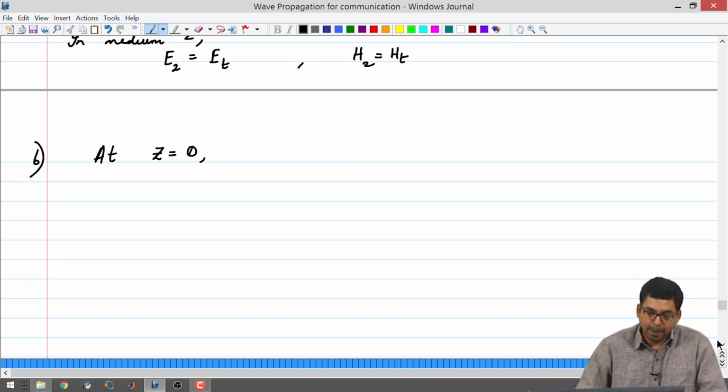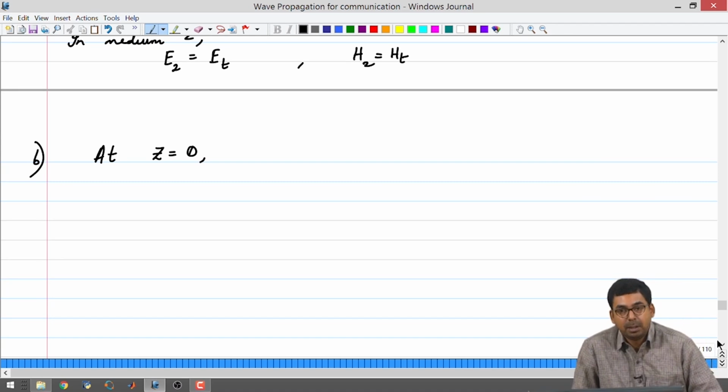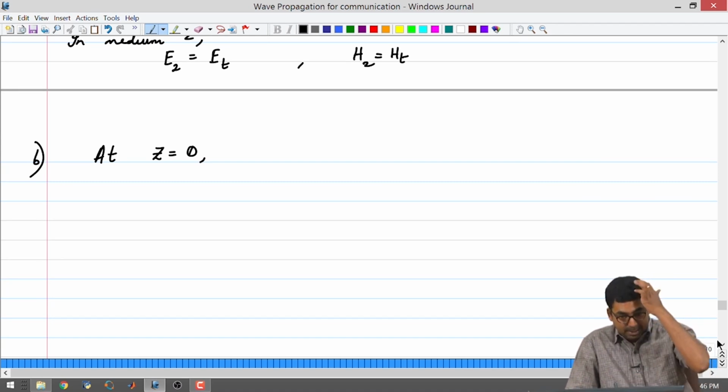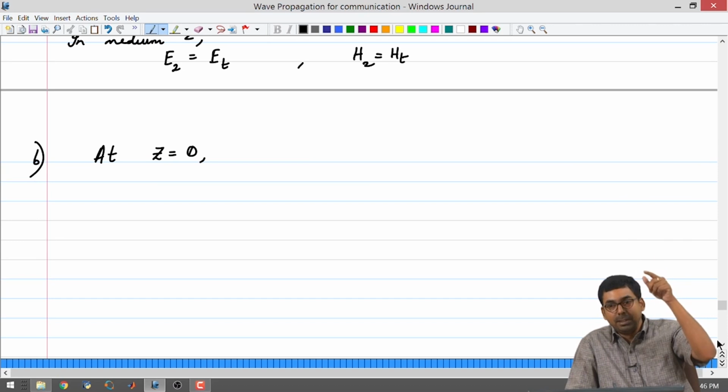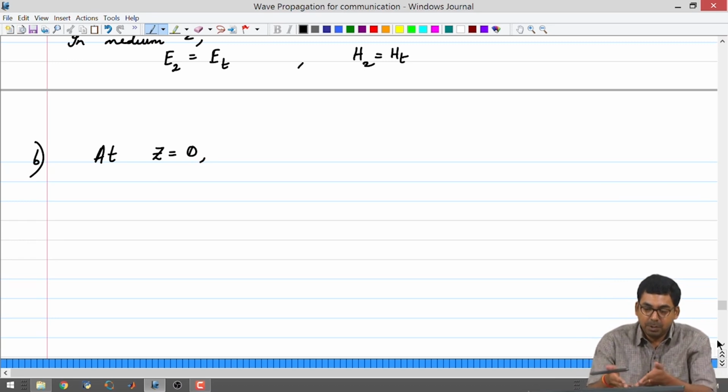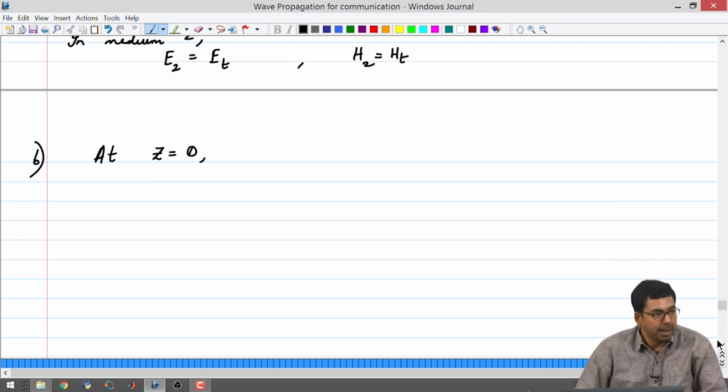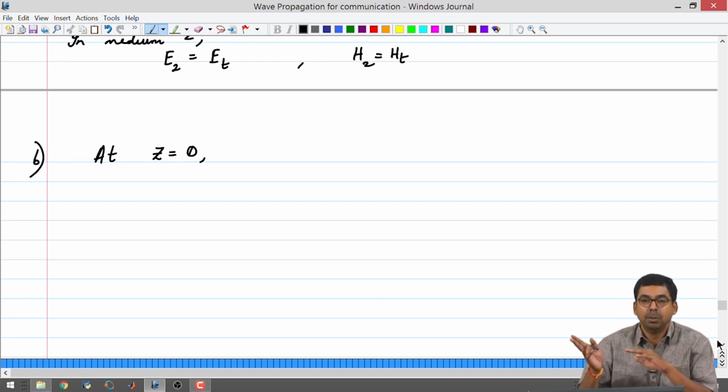So, we were saying that in the case of electromagnetic solvers where you are using the two curl equations, the two Gauss's law become implicit boundary conditions. One has to remember that, and when you are using it for interfaces, Gauss's law is very important for you to determine continuity of fields. Which fields are equal in medium 1 and medium 2, and which fields are not equal, is actually determined by Gauss's law. So, it is known as a boundary condition or an implicit boundary condition.